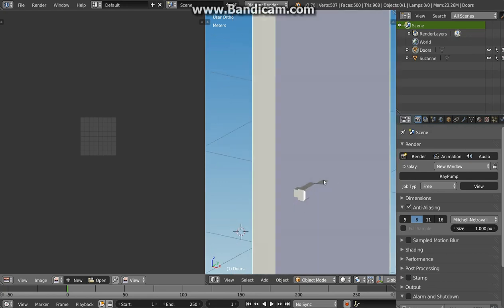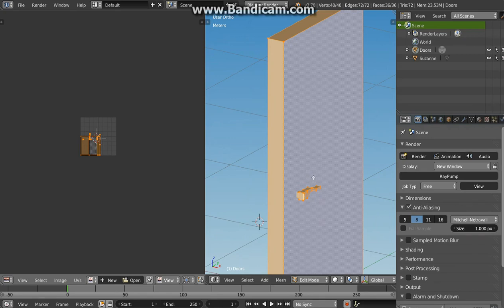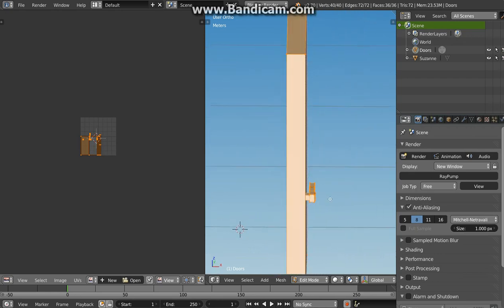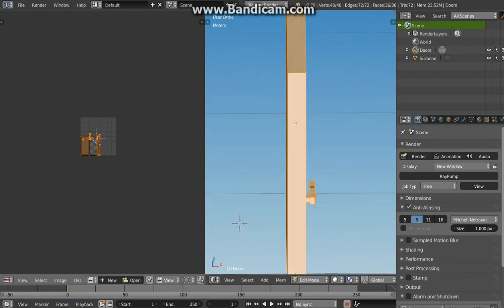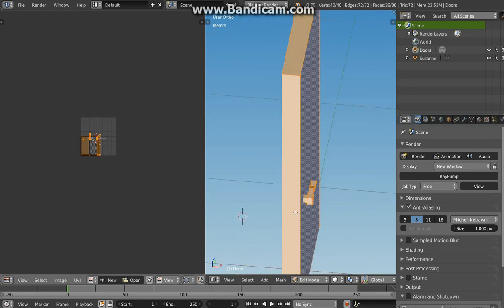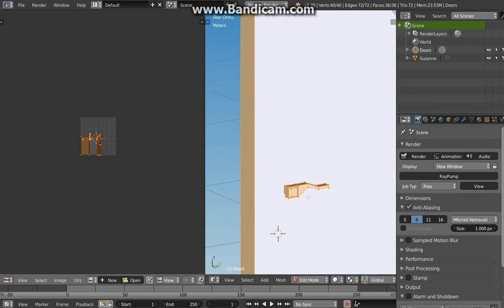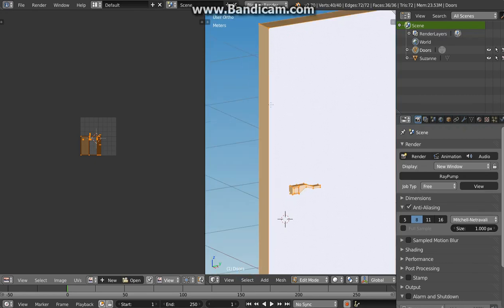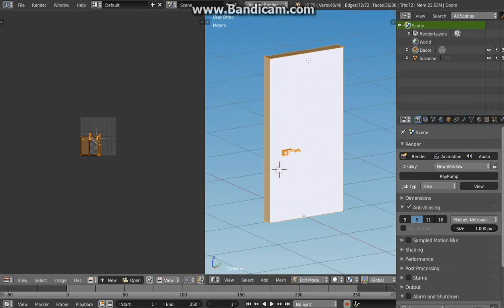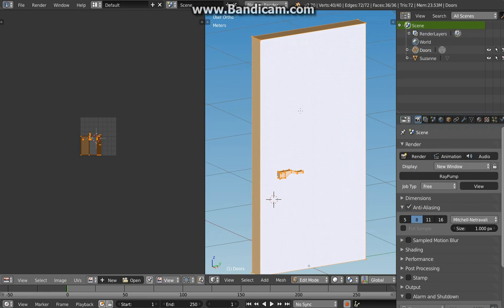The little detail should always have a higher density of vertices because it defines the silhouette of your object and it's necessary. You don't want vertices on these big planes because it's a waste of memory.